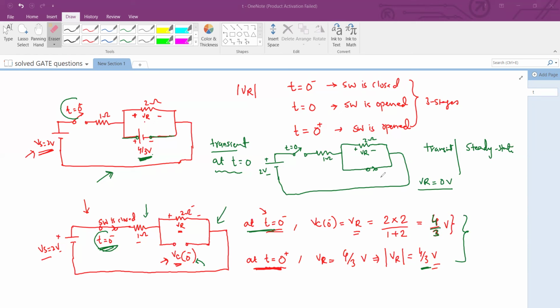If it were the inductor, as in the previous case, it would have behaved in transient as an open circuit, because it opposes a sudden change in the current through it. That's the property of the inductor. So very good points, very fundamental points about the capacitors and the inductors. And that's why they are quite widely useful as passive elements in the switching circuit. So a switching circuit can be analyzed for the transient as well as steady state conditions. That's what we did in this tutorial module.